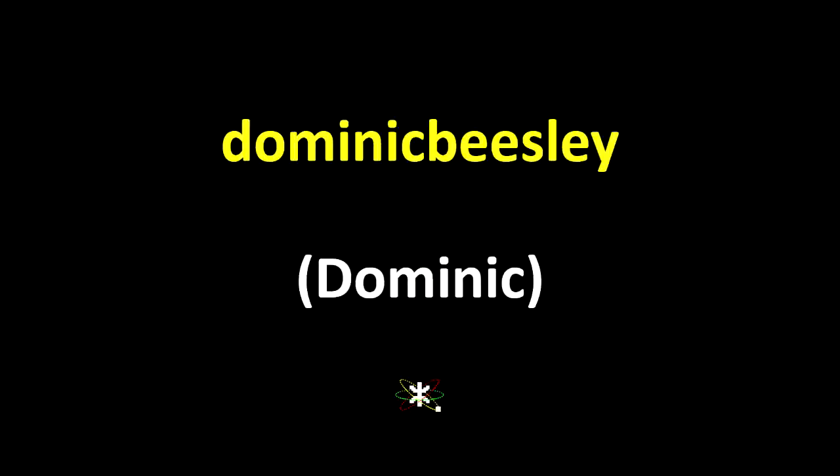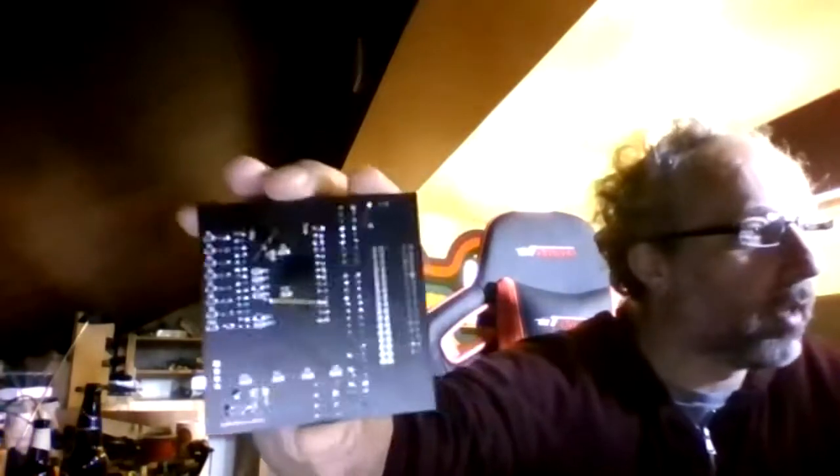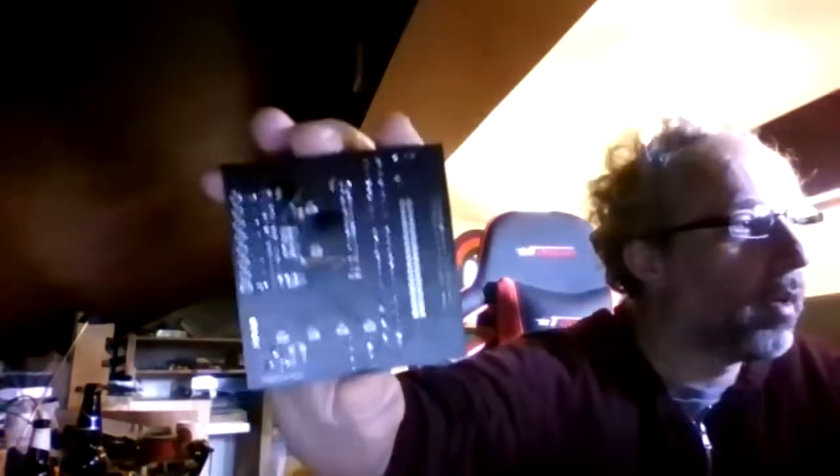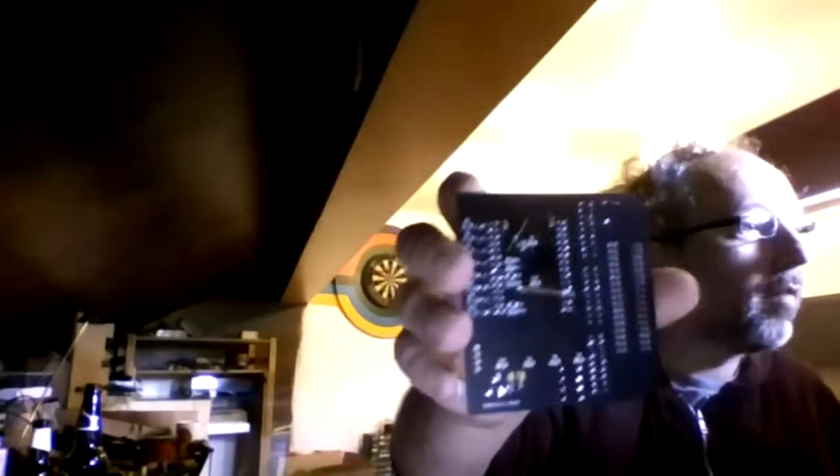Could I ask another quick one? Certainly. I don't know if you'll be able to see this. I've got a board that I was messing around with. It's a network board, which kind of works, but it uses one of these WizNet modules, and it's really fussy about the read and write select clock edges. And if there's any ground bounce or anything like that, it double selects and tends to skip a byte. So you can see on here there's a load of bodge wires and bits of solder braid that I've nailed to the bottom to try and improve things.